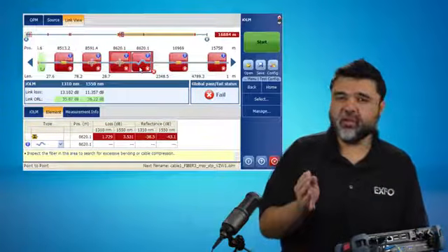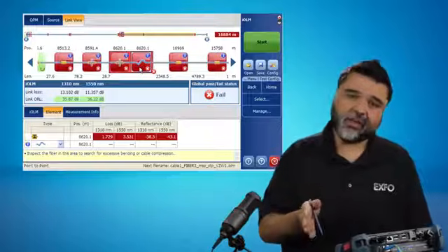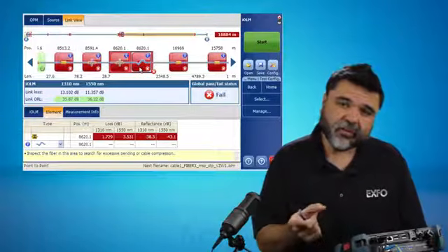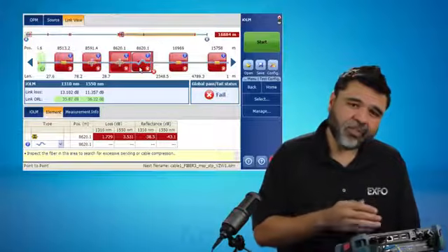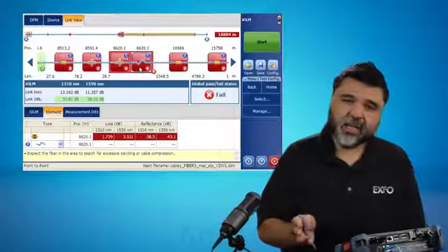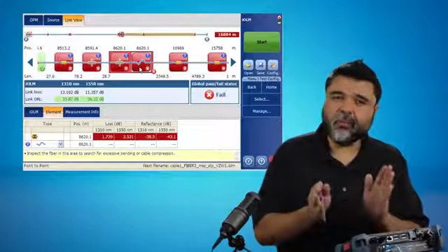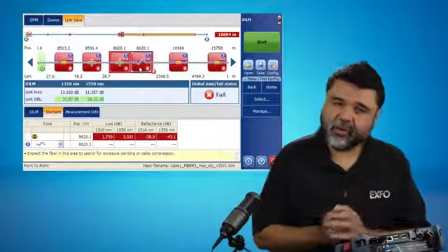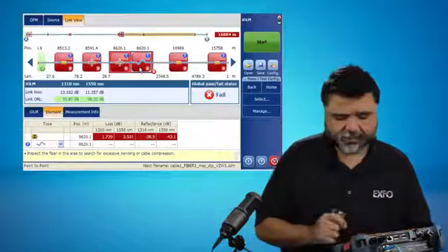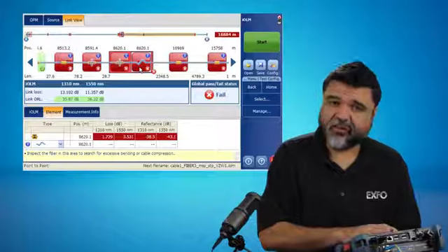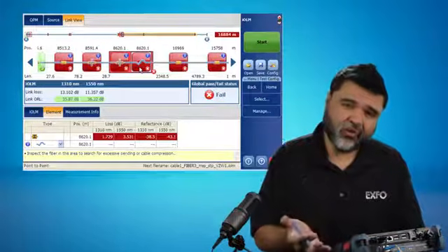And so the beauty of this software is, if you remember with the OTDR, we had to shoot multiple pulse widths. We had to go from 100 nanoseconds to 50 nanoseconds to 30 nanoseconds to be able to separate those merged events. IOLM gets around this by shooting multiple acquisitions and then comparing them and finding those discrete events that are buried within the dead zones, that are buried within the resolution issues of the pulse width. And on top of that, it analyzes the information based on the parameters that you gave it.